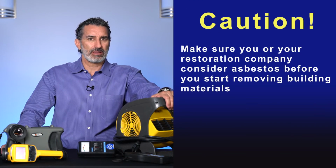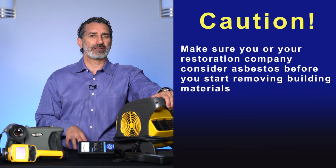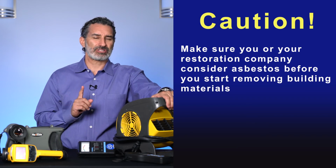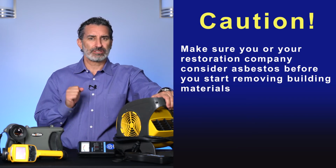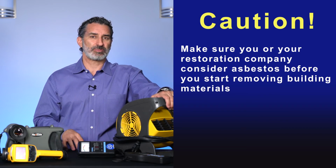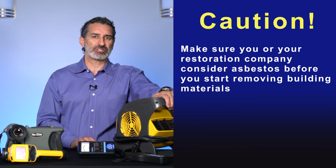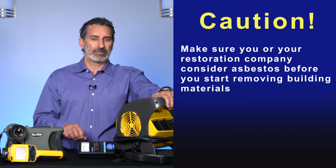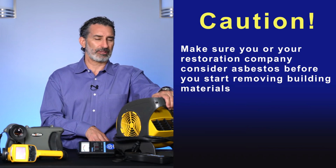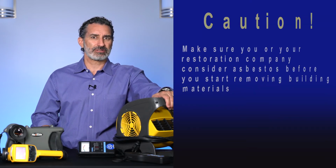Water restoration is not a federally regulated activity. Restoration companies can come to your facility and they can do this work, dry your building, but in the process go from, again, hero to zero by disturbing federally regulated materials such as asbestos. Make sure that you or your restoration company consider asbestos before you start removing building materials, because you don't want to be responding to a non-federally regulated event only to disturb federally regulated materials.